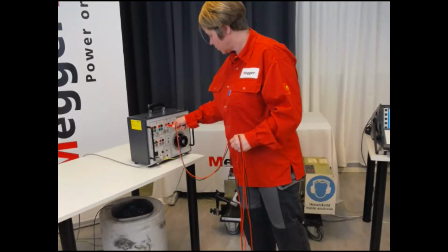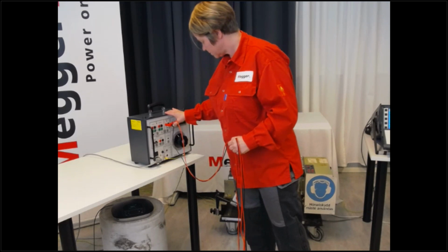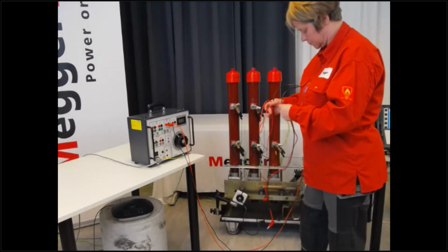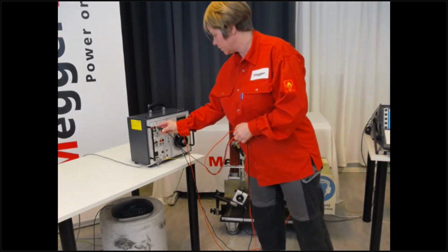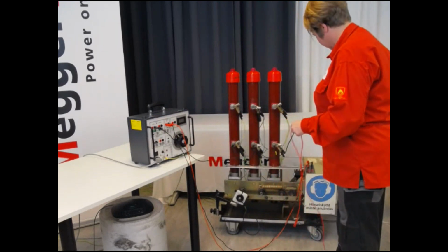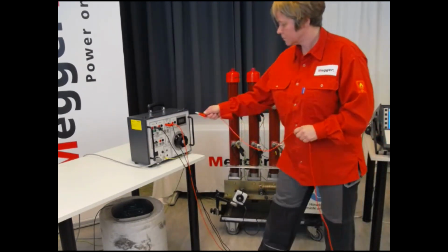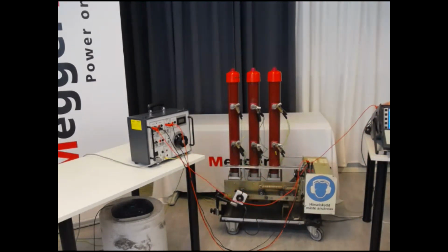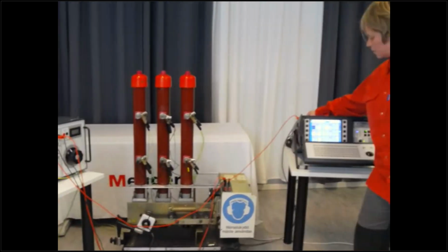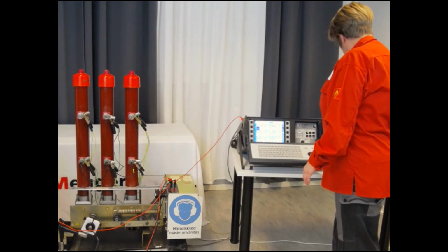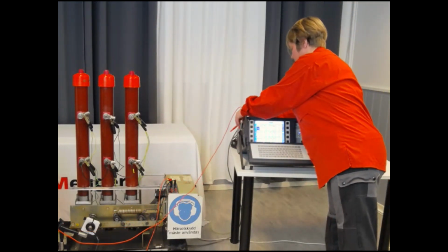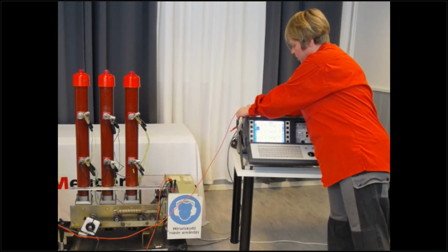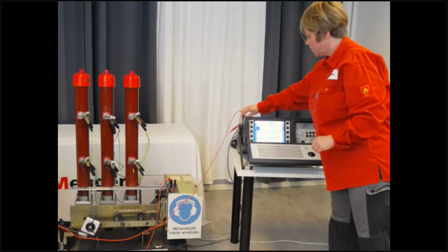I need again to connect the motor to my object. I need to get minus to the object and plus to my instrument. I also need to link here because I'm using different channels. So I need to link, so I get supply for both close and open. Since I also want to measure the voltage, which I didn't mention, I need to connect the minus also up here.